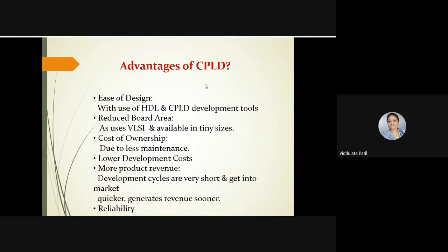Okay, because in this Altera MAX 7000, we have JTAG technology, also boundary scan technology. That means on-chip testing can be done whenever we are using a CPLD, and that is why you will be sure, before fabrication, that whatever we have designed is correct. Okay? So that is one more advantage of using CPLD.